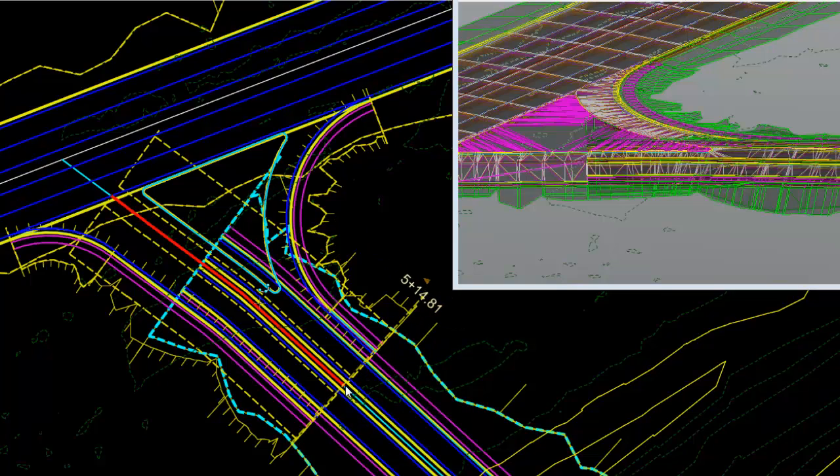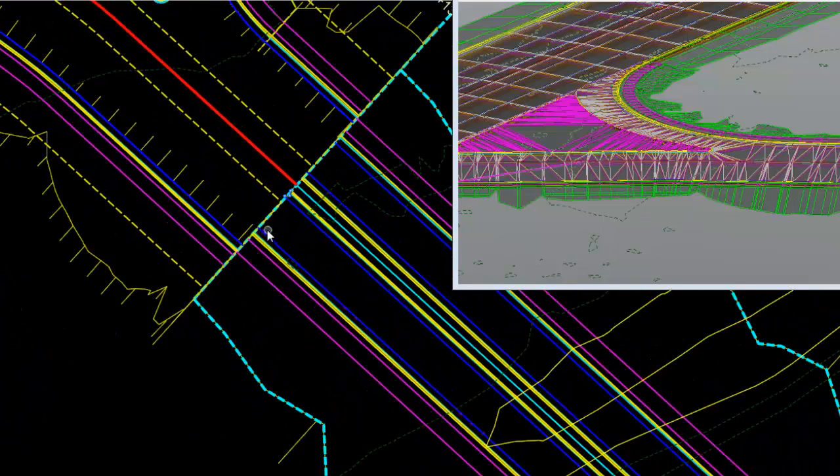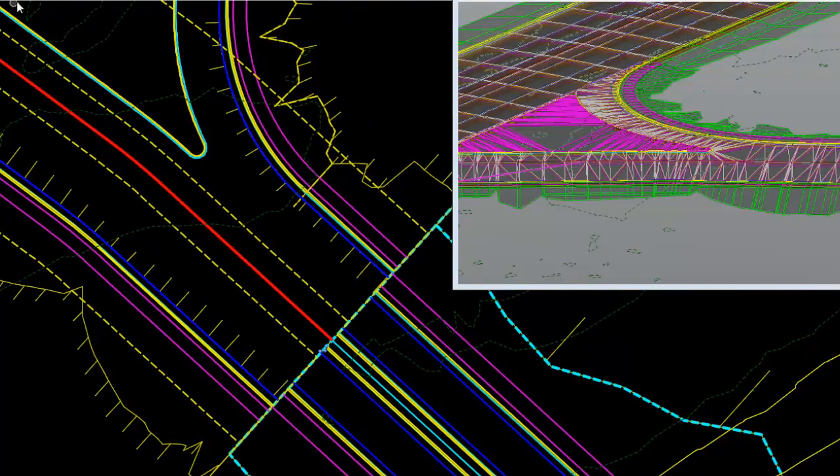And typically we'll snap that. If we decide to move it back, we'll snap it to the center line of the cell. And this way, if we extend or shorten the cell center line, the corridor will move with it. Now, some modifications we can make.